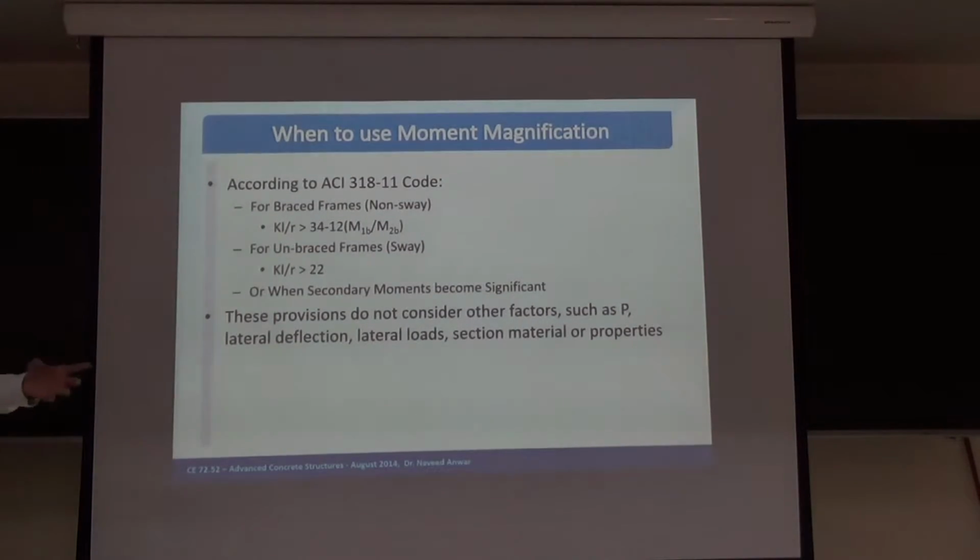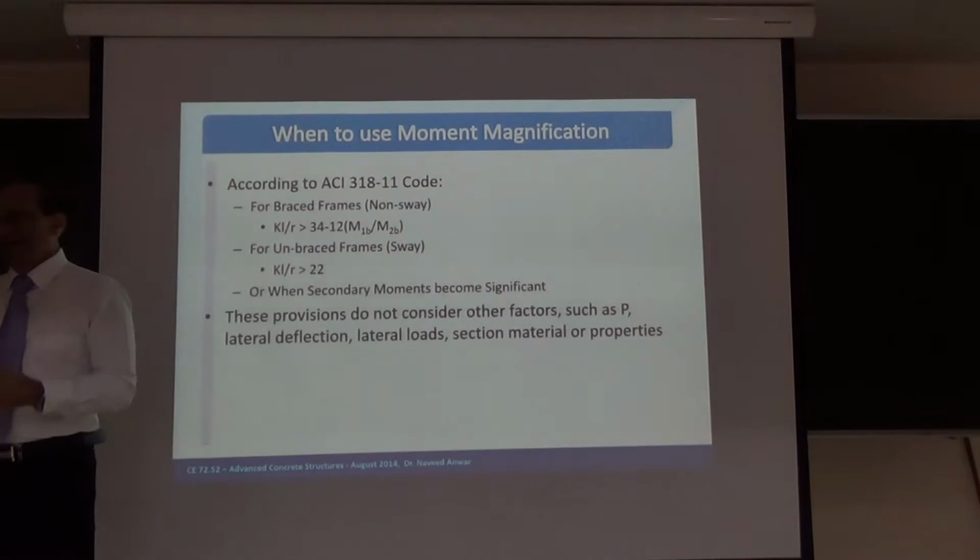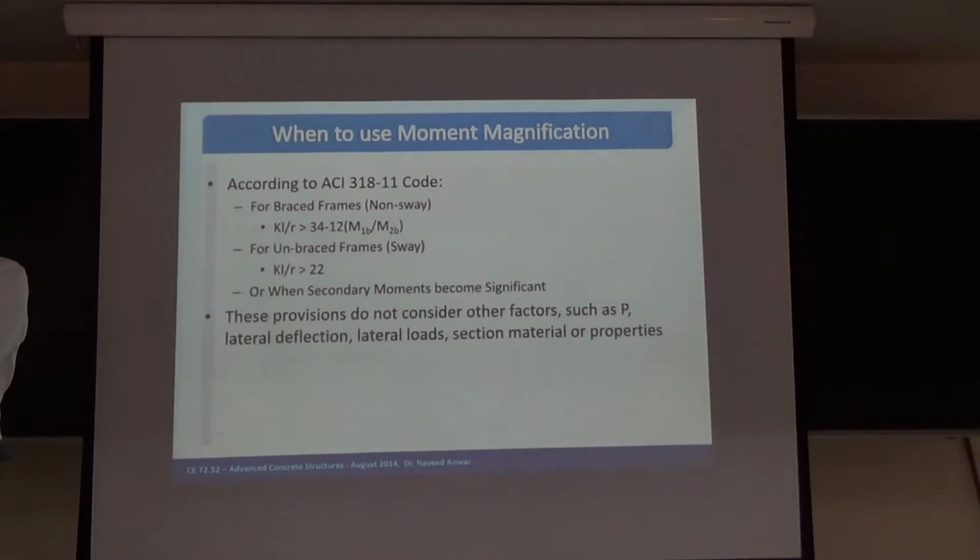Second is that normally for tall buildings we have big shear walls, elevator walls, which prevent the building from swaying. So buildings become non-sway because the shear walls control the sway. Big shear walls or big elevator walls do not let the building move too much between two floors. So the sway between two floors is very small.